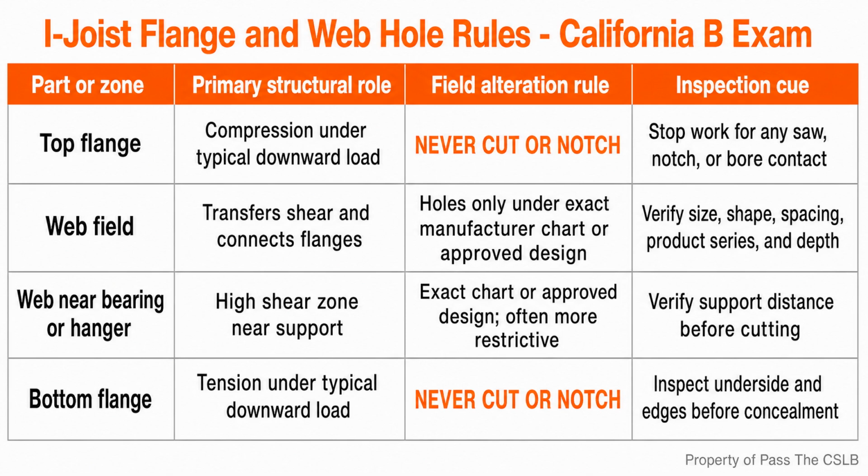A useful field sentence is this: flange means stop, web means check. It is short enough to say during rough-in, and it keeps the crew from confusing an allowed web opening with permission to touch the flange. I want to put that sentence into a realistic coordination decision.